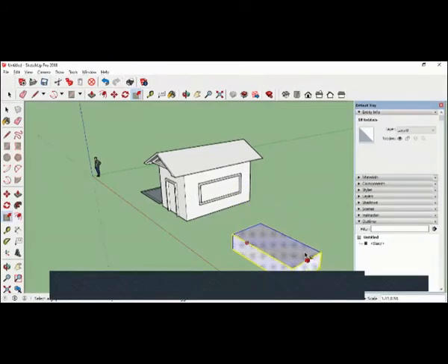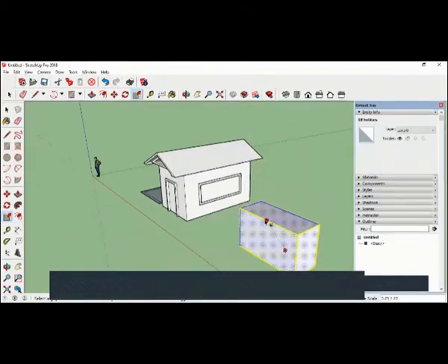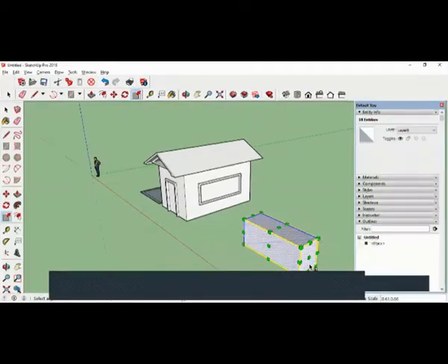So you can give whatever value you want. And if you click here, it is telling you green and blue. Green direction, blue direction. This is how you use the scale command. I hope you got some idea. When you click the corner, you get the uniform scale. When you click the center button, you can increase in one direction. And if you click the middle button of the top or bottom, you can increase or decrease in 2 directions.